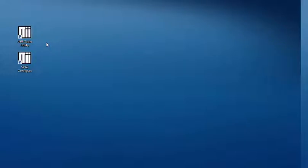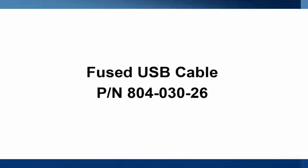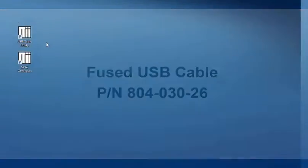Before going on about the USB cable utility, I'd like to first make mention of the USB cable itself. Over time, we've had two versions of the USB cable. The earlier version is readily identifiable by a yellow label along the length of the cord, and that yellow label has the part number of the USB cable on it, and you can see the part number here. The current version that we are distributing is called the fused USB cable, so called because there is a fuse in the small USB shell for intrinsically safe applications.